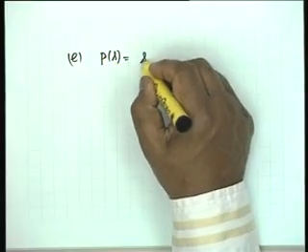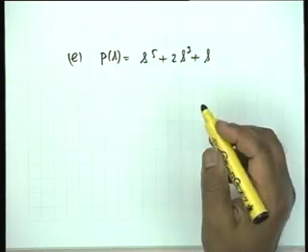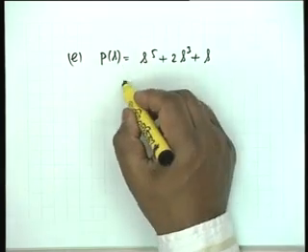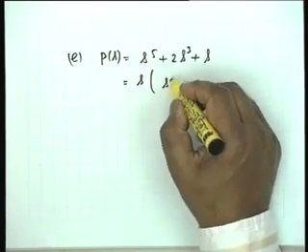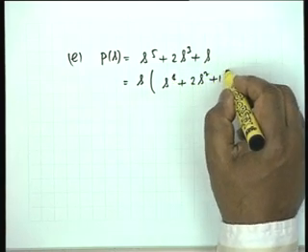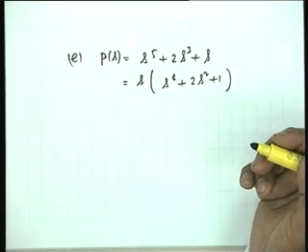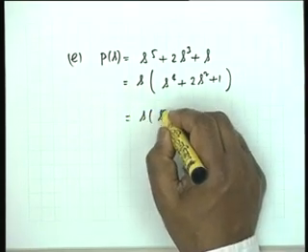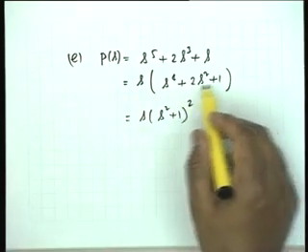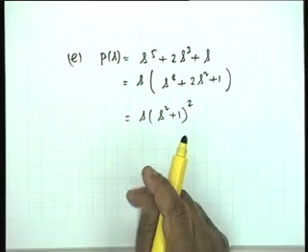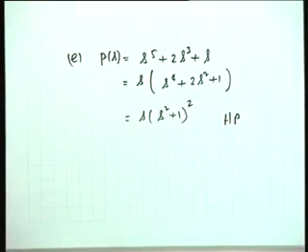We skip D, we look at E, which is also purely odd. E is s^5 plus 2s^3 plus s. We don't differentiate this first. What we do is simplify this by taking an s common, and I get s^4 plus 2s^2 plus 1. Do I have to carry out continued fraction? Isn't it obvious that this is s times (s^2 plus 1) whole squared? Had I done the continued fraction expansion, what do you expect? There would have been premature termination. I would have got only one quotient. Anyway, you can do this. Therefore, this is a Hurwitz polynomial. F I have already done in the class, so skip that.